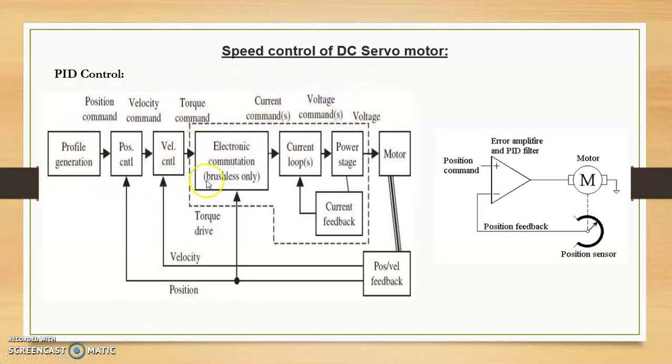For all that, we are using a DC servo motor, and we have a feedback system collected from your sensor, and from that it is given to your velocity control operation, and it gives the displacement change operation or position operation. Depending upon the application, all the signals are received from the system, and by using this PID controller, the total system will vary the position and velocity with respect to the current and voltage control command, and that is given to your DC machine.